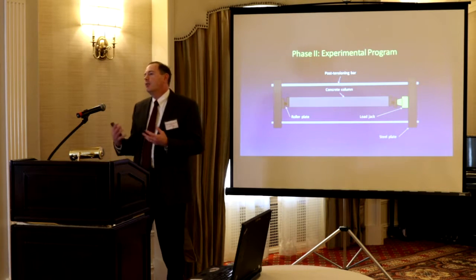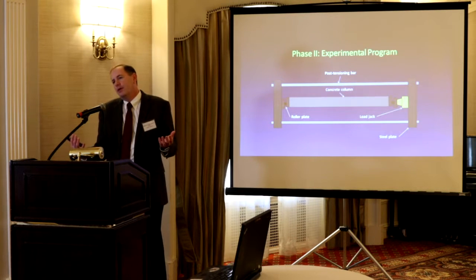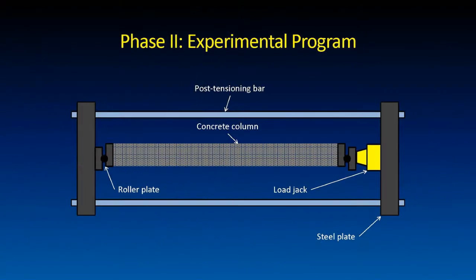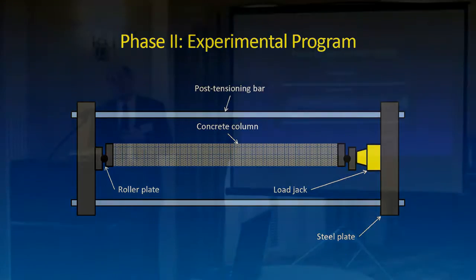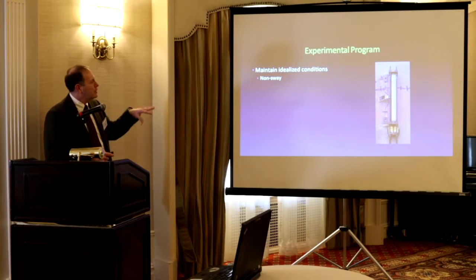We only had a certain number of columns to base our analytical work off of because there was not a lot of columns out there. So we wanted to test more that tested the bounds. And so this is our loading setup. We have steel plates here, we have rods here, we can lock them down, sustain the load. We wanted to look at sustained load effects also. So we maintain idealized conditions to make it simple to compare.